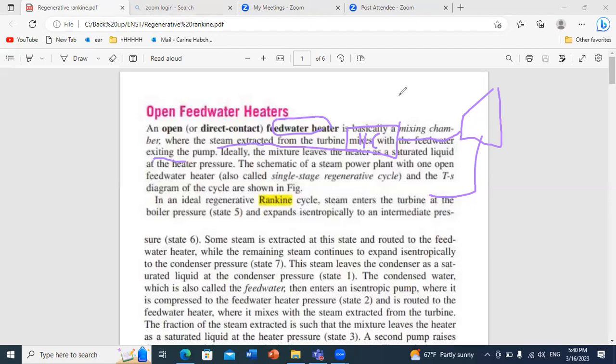If the source of this heat is another cycle, like the gas turbine system, where you have high exhaust gases, it's an open system. In this open system, you have a high temperature of gases that you can profit from. So you can pass these hot gases through the boiler of your conventional cycle, and this is the process of heat recovery. So you are using waste heat from a cycle to operate another one.